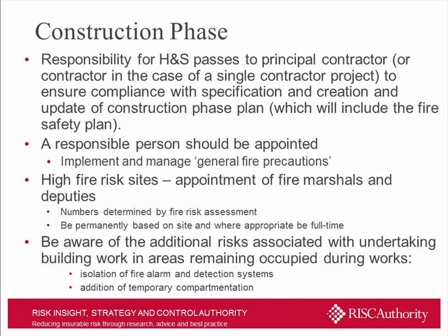And there's a requirement there for them to ensure that there's a construction phase plan for health and safety, which will include the fire safety plan as an element of that. There's a requirement for a responsible person to be appointed. Now, that sort of flies in the face of legislation slightly, because the regulatory reform order, for example, places the requirement for managing the general fire precautions aspects of fire safety on a responsible person, but it doesn't define who that responsible person is. Very often it won't be a named individual, it will be a board of directors or a board of trustees or something of that nature.